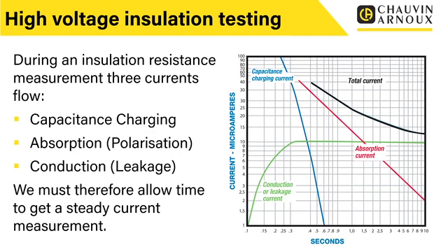But the good thing is, as you'll see when we get into the testing techniques, we can use these to our advantage. We can use these charging currents and the fact that this is a known state, and we can use this to tell us about the state of the insulation as well, which is really good.